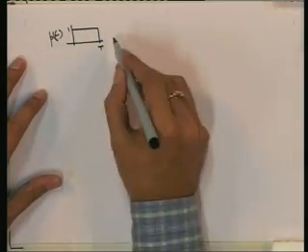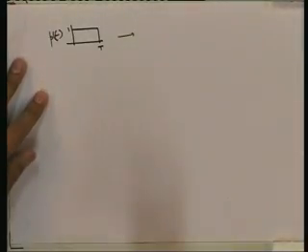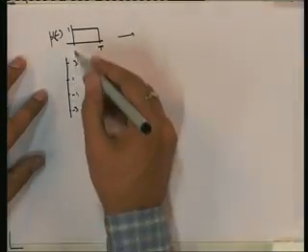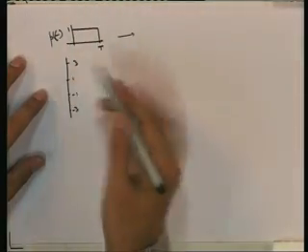integrate the received signal. So, if we transmit 1 or 0, we will have two levels, or if you have M-ary PAM, then we will have many more levels, M number of levels. So, for 4 PAM, for example, we can have -3, -1, 1, 3. We can have these 4 levels, and then we can multiply those numbers to this pulse and transmit depending on what we want to transmit.